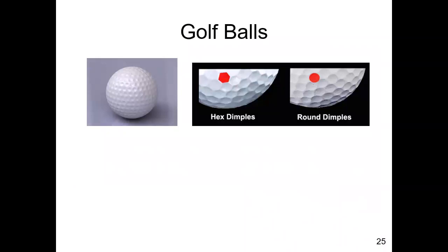Well, the dimples take what normally would be a smooth sphere and roughen the surface and create a turbulent boundary layer of the whole sphere. That turbulent boundary layer makes the wake zone smaller and has more reattachment, and therefore dramatically reduces the drag coefficient, which translates to: if you hit a smooth surface golf ball, it won't go as far as this one with the same hit. That hit is basically the restoring force, or the opposite of the drag